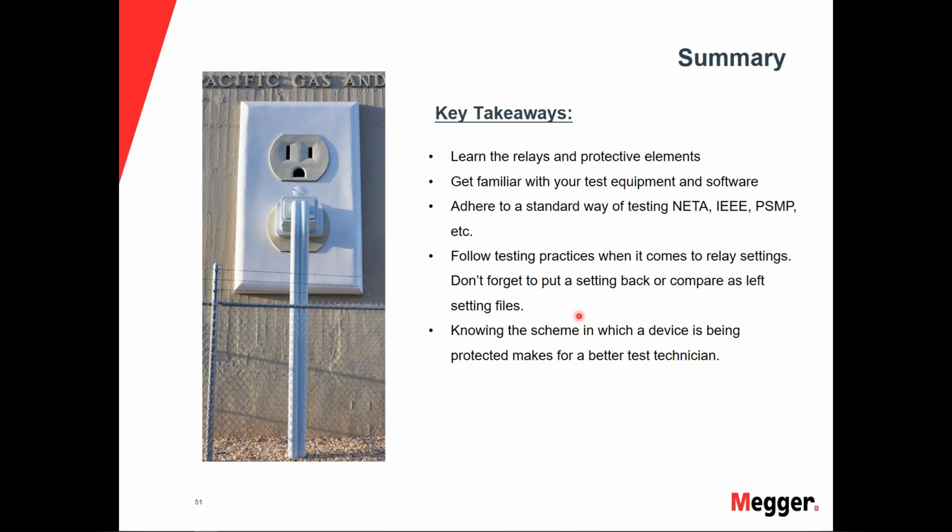Follow the testing practices when it comes to relay settings. Pull them before you get to the relays. If you have electromechanical relays, we all have phones. Take a picture, write it down, whatever it takes for you to remember what the settings are, and do it before you touch the relay. So if you have to take a picture of it, if you have to write it down before you pull it out of the panel, great.